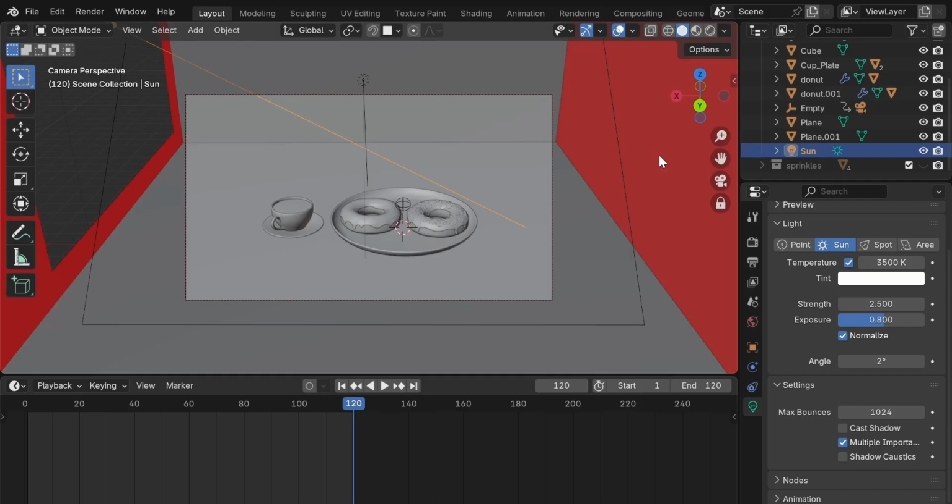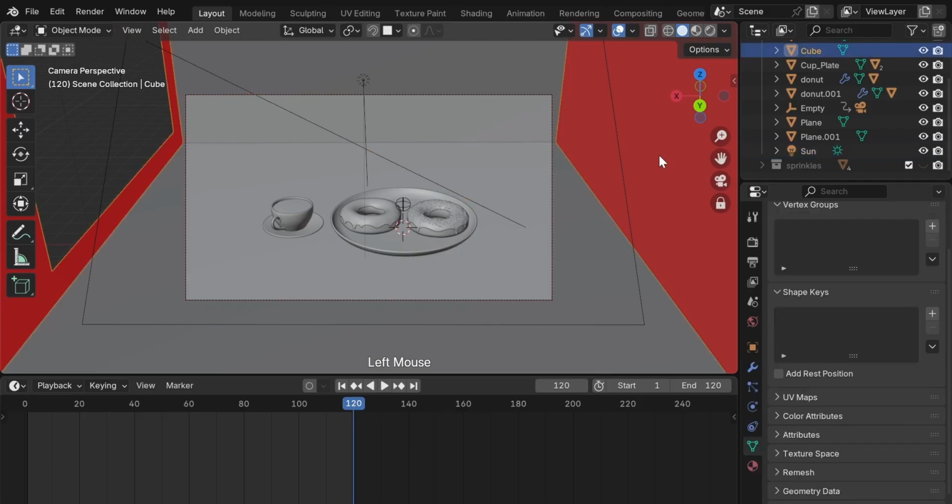Shaders, lighting, and even the camera all expect surfaces to face outward. When normals are flipped, light behaves incorrectly. Materials may look broken, and during rendering, strange artifacts can appear, often much later when they're harder to trace. So if you see red faces, never ignore them. Pay special attention to the inner cube in our scene. Remember, we created that cube while the camera was outside of it, which means the camera expects the cube's outer faces, not the inner ones.